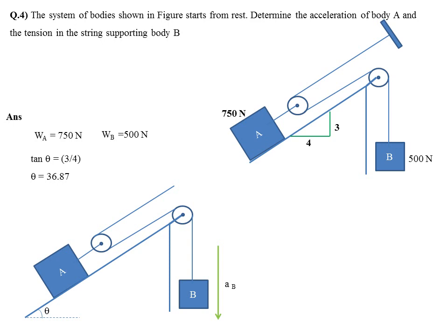Before going to this problem, if you observe the question, there is nothing mentioned about the friction, right? The friction value is not given, mu is not given. So this problem you can solve without considering the friction, without considering Fa for the block A. Okay, so Ra will be there. Ra is not 0, mu is 0, that's why Fa equal to 0. Okay, don't take Ra as 0. Ra is there, the reaction provided by the surface on A is there, mu is actually 0, that's why Fa equal to 0.